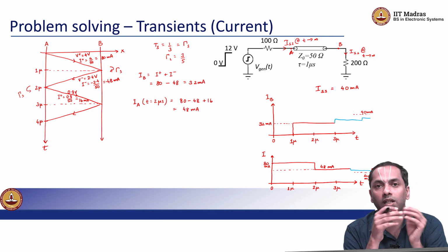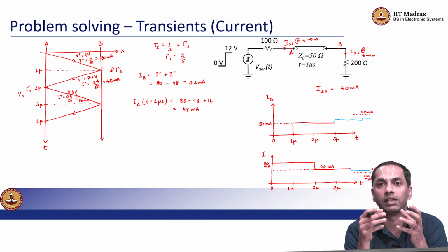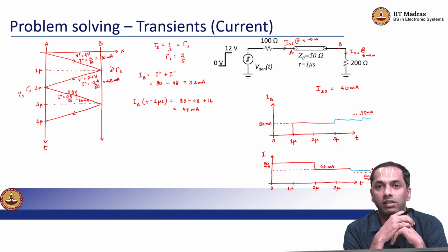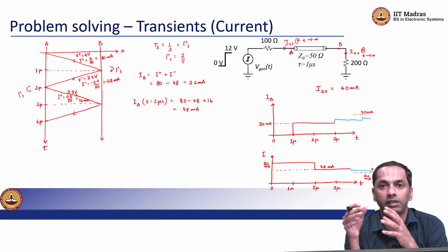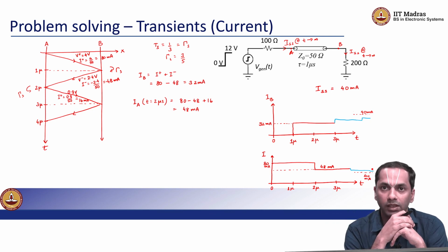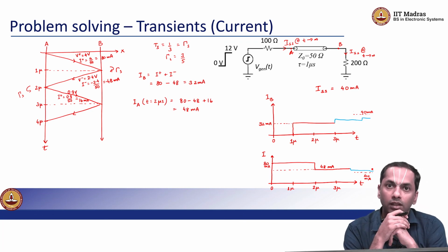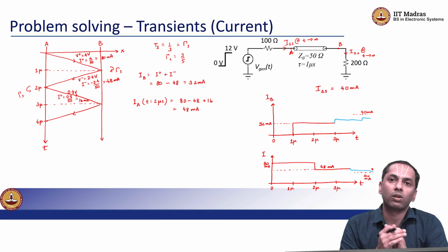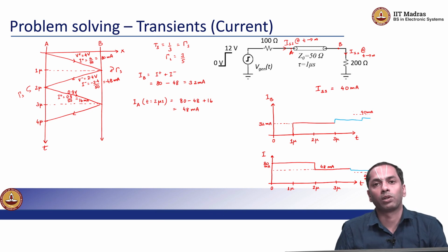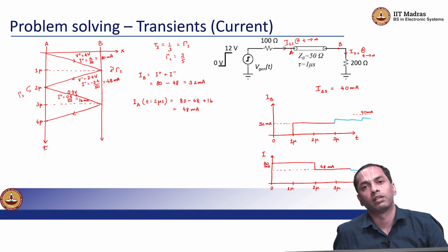You can think of currents in terms of the magnetic fields that are storing the energy within the transmission line. You are slowly charging up all the inductors, and then you are doing this in a very time delayed manner, right. So, while this is all great, okay, I have taught you the mathematics behind it. You've been given an algorithm, by drawing these echo diagrams to essentially estimate what is the voltage and current.